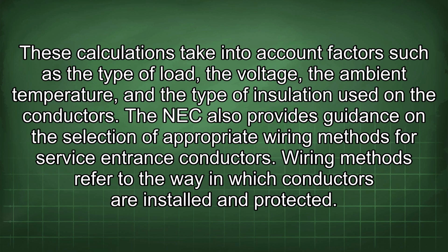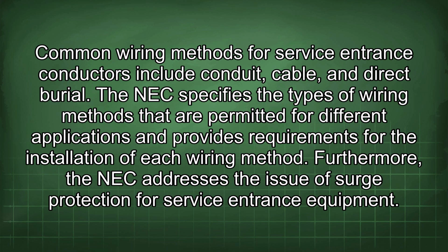The NEC also provides guidance on the selection of appropriate wiring methods for service entrance conductors. Wiring methods refer to the way in which conductors are installed and protected. Common wiring methods for service entrance conductors include conduit, cable, and direct burial. The NEC specifies the types of wiring methods that are permitted for different applications and provides requirements for the installation